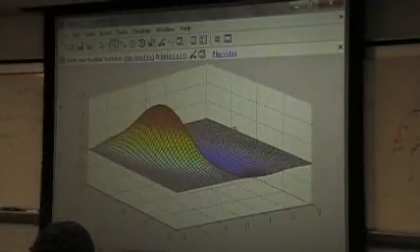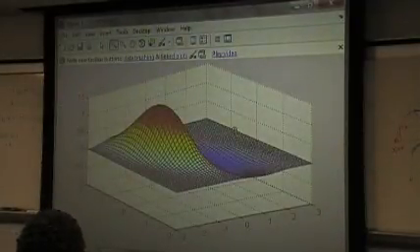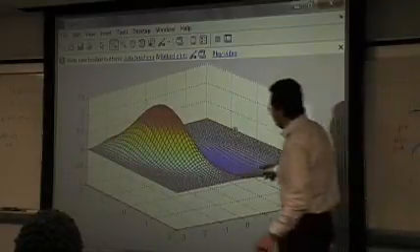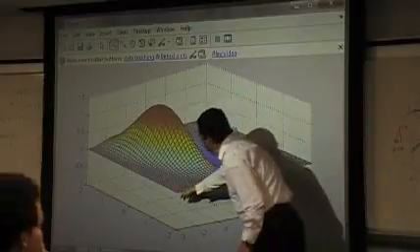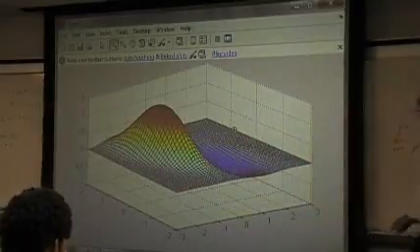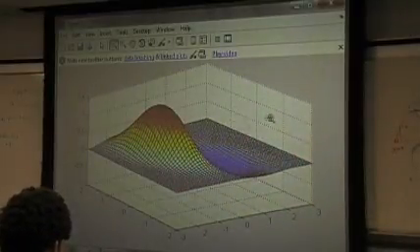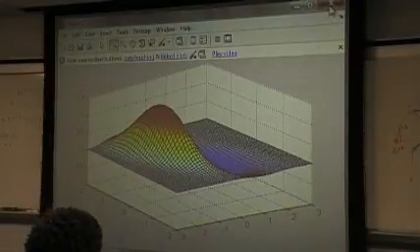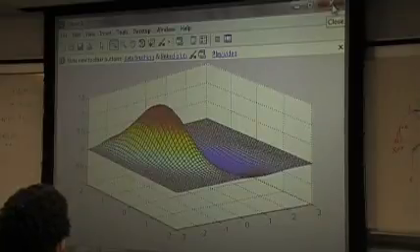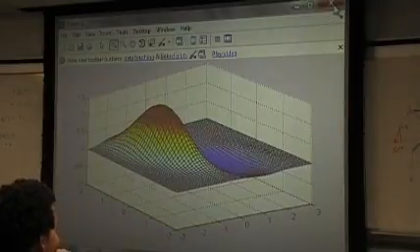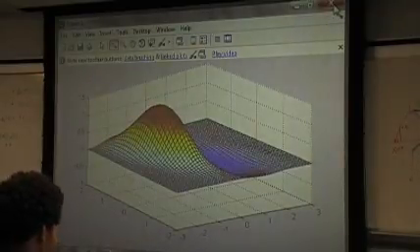This is the interpolation result, but the interpolation points are selected automatically. You do not have to specify the space between points. So this one is obtained by the spline interpolation method. And if you are using a B-spline, you will normally have better results.